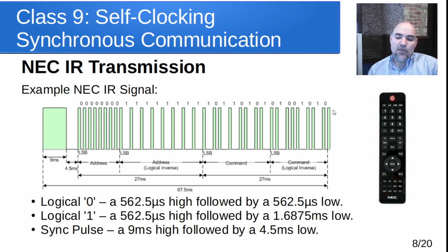So if you actually had a little infrared transmitter, it would be really easy to write code on the Arduino that sent out these pulses that did things like turn on your TV. You just have to know what address your remote for your TV uses and what commands each button uses. And if you had an infrared receiver, you could hook an oscilloscope up and press these buttons and watch this stuff show up on the oscilloscope. It's a really cool thing, but notice it's using those pulses.